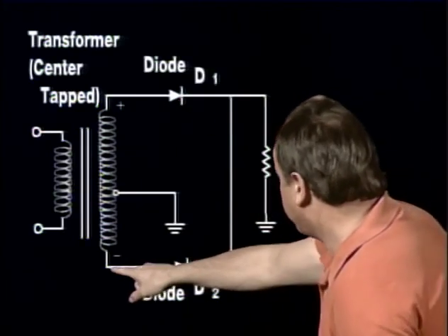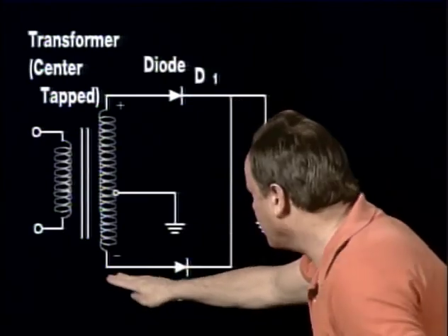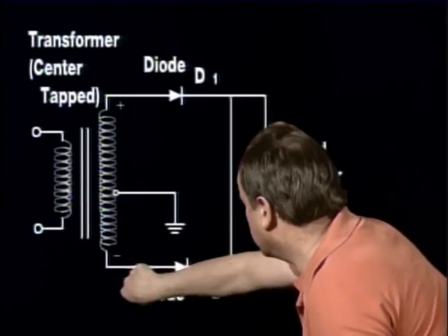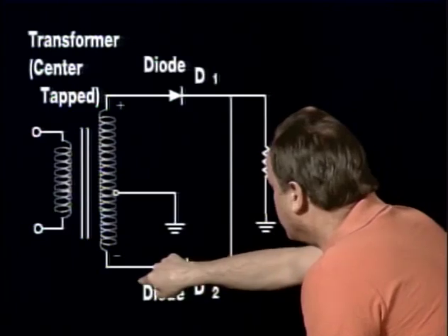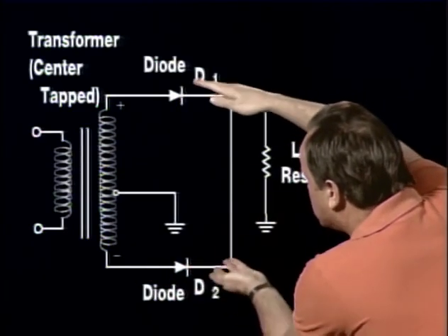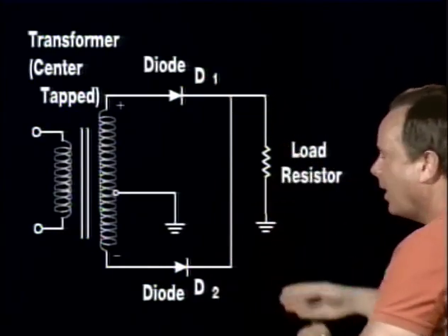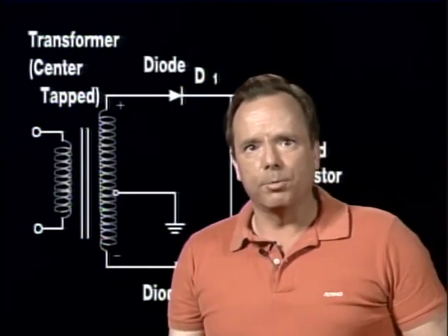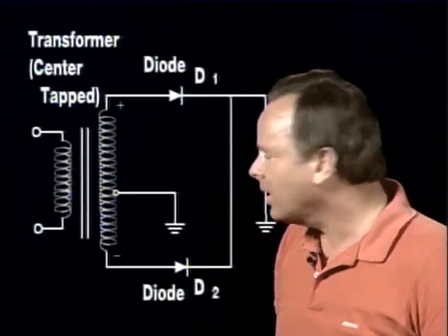Now if you had opposite phase alternating current down here reversing itself, this diode lets it only go in one direction. And if it's the opposite phase, it's going at a different time than this is, so that these two join to be direct current going out this direction, and that's a rectifier, and that's the whole purpose of it, and diodes are used in rectifiers.